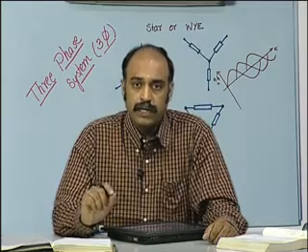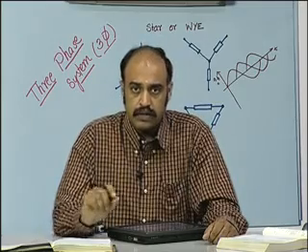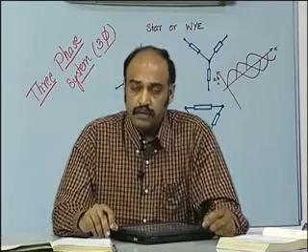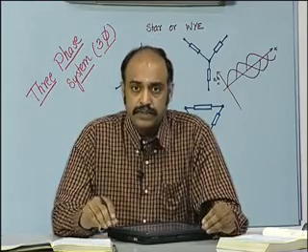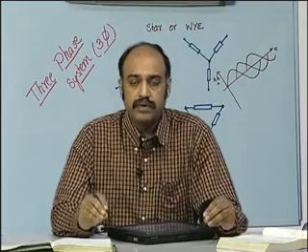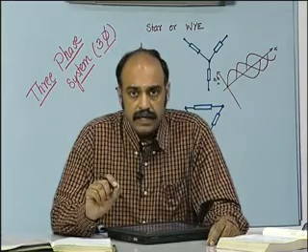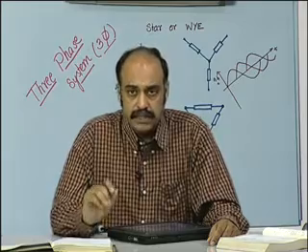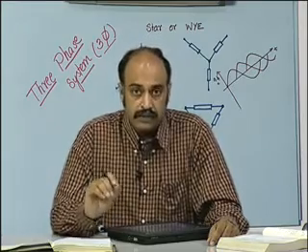And then we eliminated the common neutral wire, which is the 4th wire, and made it into a 3-wire system, with the assumption that the loads were balanced, and because the loads were balanced, the instantaneous current flowing through the neutral wire, I A plus I B plus I C, is always 0.